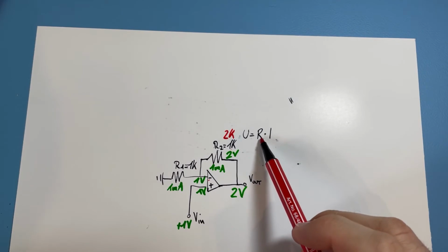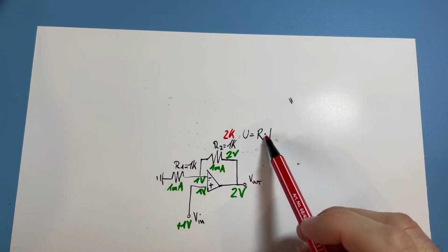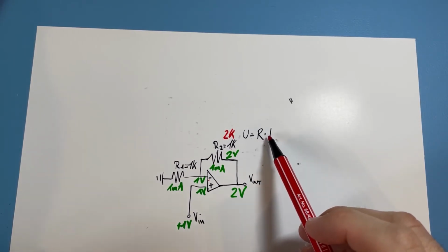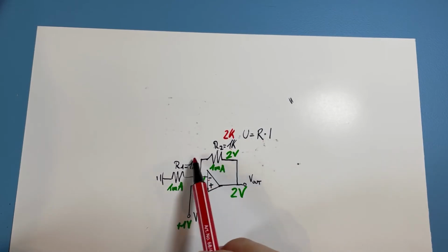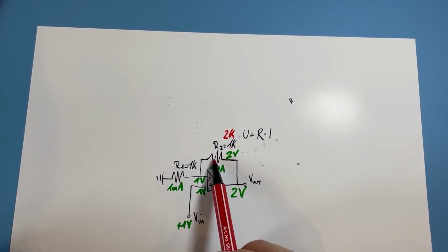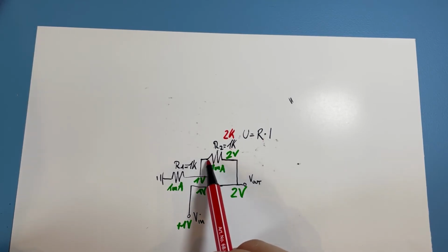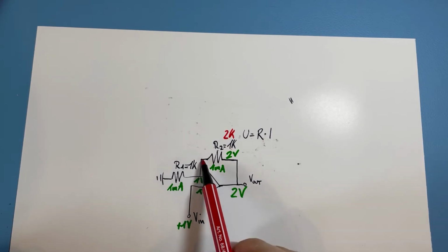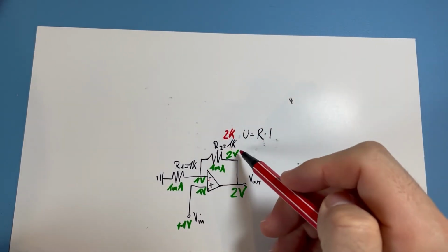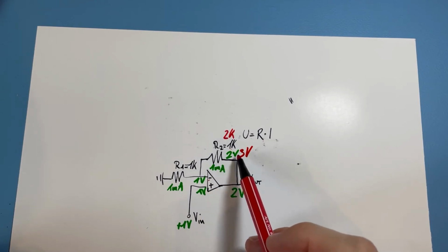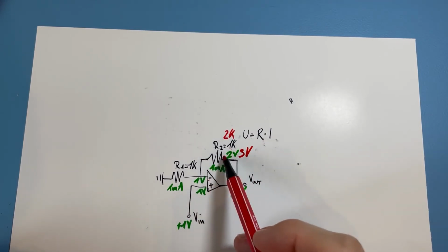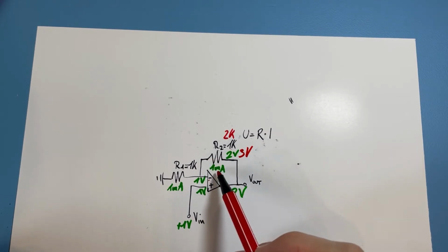And again, voltage equals resistance times current. But now the resistance is 2 kilo ohms, but the current is still 1 milliamp. And so we have a 2 volt drop over this resistor. So being here 2 volt higher to be able to flow from 2 volt here to lower voltage, the 1 milliamp. And then, okay, we have 1 volt here, we must be 2 volt higher here to the right. So that is 3 volts we have at the right side. 3 volts minus this 1 volt means a 2 volt drop over this resistor, 2 volt leading to 1 milliampere